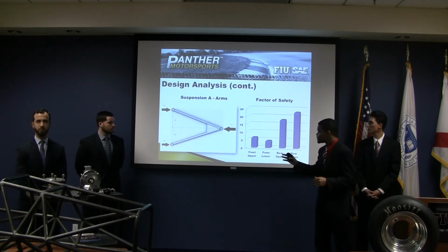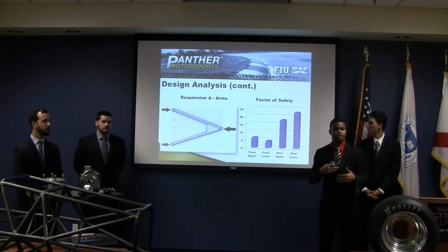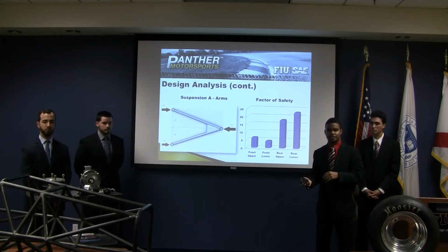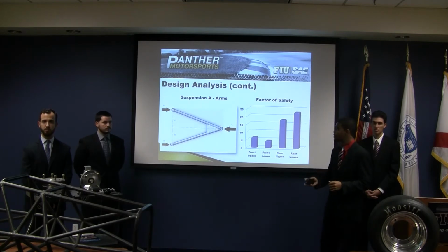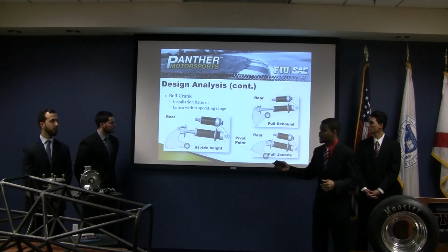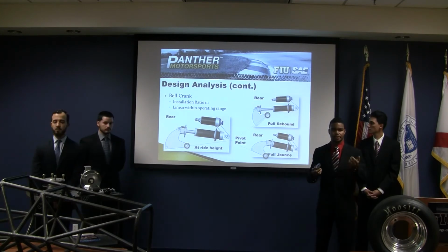Also notice these factors of safety are relatively high, and this is because we're using off-the-shelf materials and we don't have exact control over the thicknesses of the tube members. And finally, a motion analysis of the bell crank and the shock and springs.